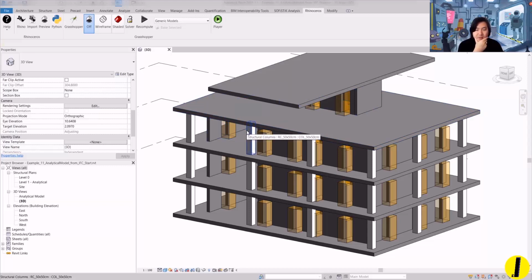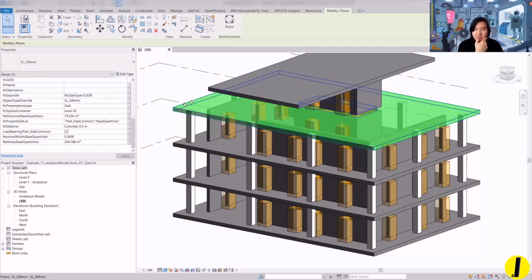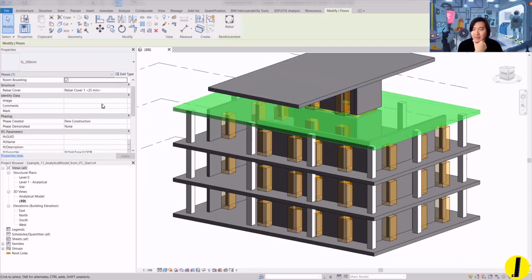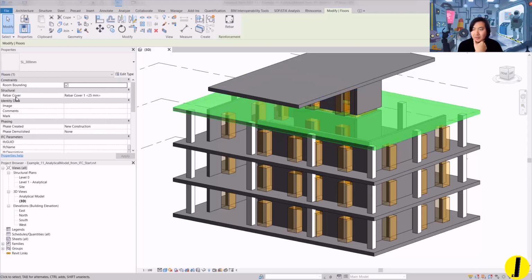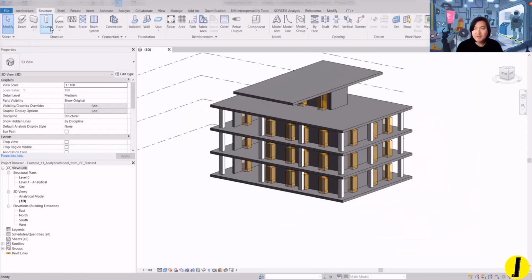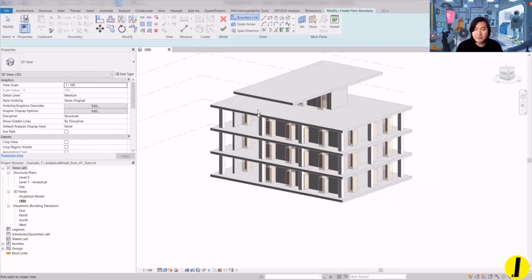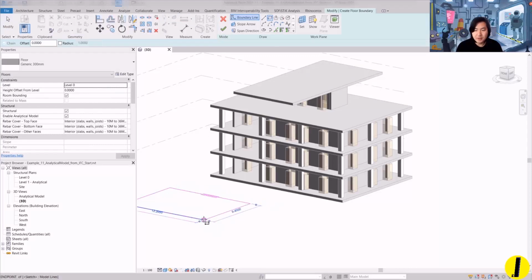What could be interesting is that even though in Revit it shows as a floor, unlike a normal one, with this imported IFC file we cannot mark it as structure, and we cannot enable the analytical model. You remember, if you have a normal Revit wall or floor, which we draw as a structural floor, I'll just quickly draw one here.